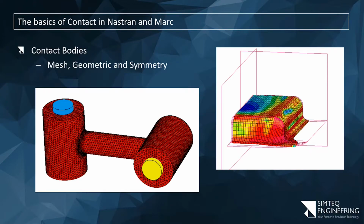An example would be if I have 100 bolts in my model, I can make all of those bolts one contact body. So at first glance, no, it's not a body. As I say, contact group of elements would probably make a bit more sense. But think of it this way, for every one of those elements, Marc or Nastran simply finds the outside faces to determine which nodes and faces can make contact. So that's it. A contact body, as we define it, is simply a convenient grouping of elements that can make contact to something else.